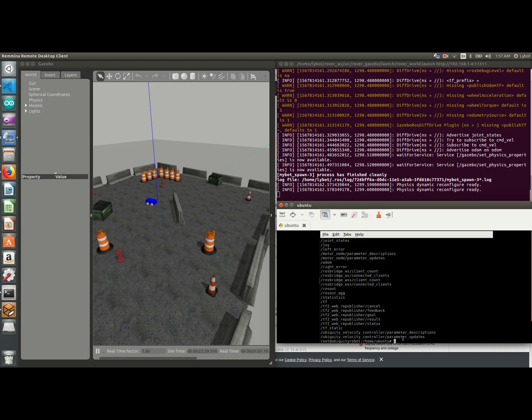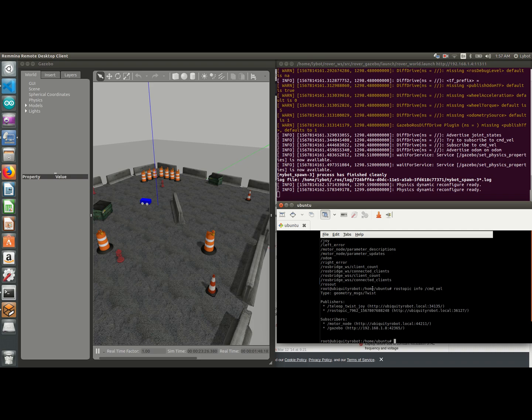So now, in order to control this URDF robot, we should manipulate the values of the cmd_vel topic. The way to do this is, let's check the information of this topic, rostopic info cmd_vel. By writing this command, we will check the information of this published topic. We can see its type, geometry_msgs/Twist, and we can see the publisher and the subscribers that are already running on both nodes.